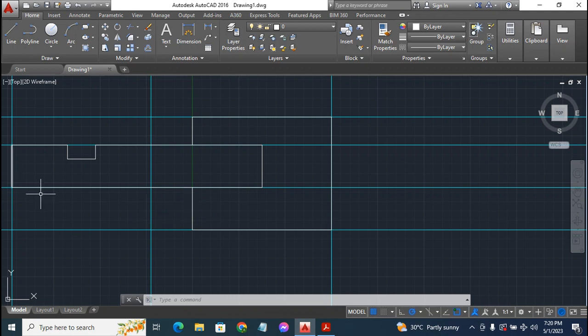So it then means that this third rectangle has to be inclined at an angle of 60 degrees. So we have to rotate this third rectangle here at an angle of 60 degrees. We rotate it in such a way that the angle between this very base horizontal line of the third rectangle and this vertical construction line will be 60 degrees. Then when we sum it up together, we'll have the actual angle we need between this line, which is 150 degrees. Okay, so let's do that.